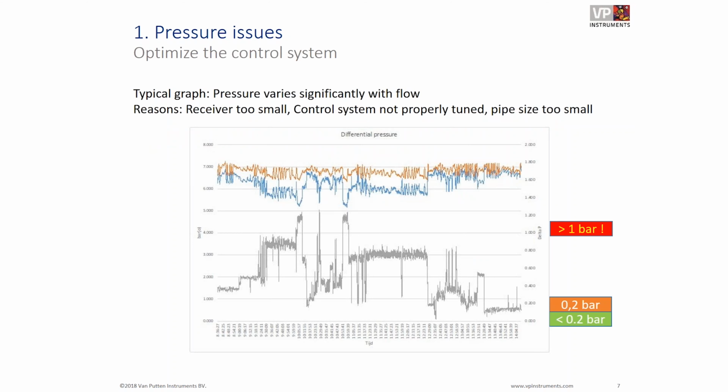And well, how does it look in practice? This is an example where the red line is from the red flow meter, measuring flow, pressure, and temperature, 3-in-1, and the blue line is from the other one. If you subtract those two, the difference is on the right axis, and you can see the pressure loss. There are peaks up to 1 bar, and on average there might be about half a bar of pressure loss in this system. And this is quite a huge saving potential. It's about 7% of the energy bill if you're able to save 1 bar in your overall pressure.